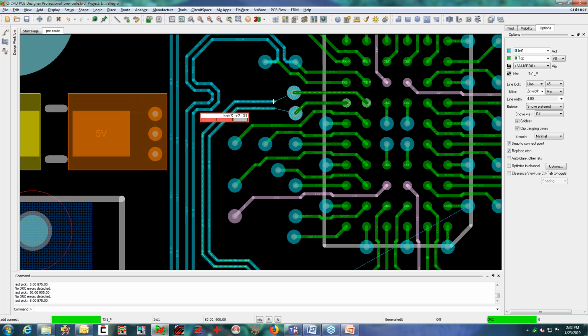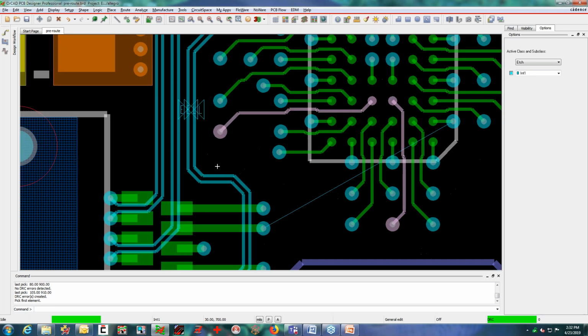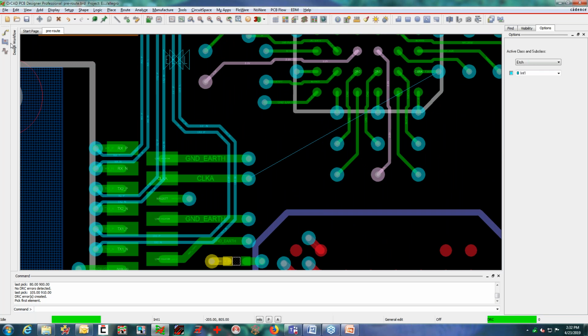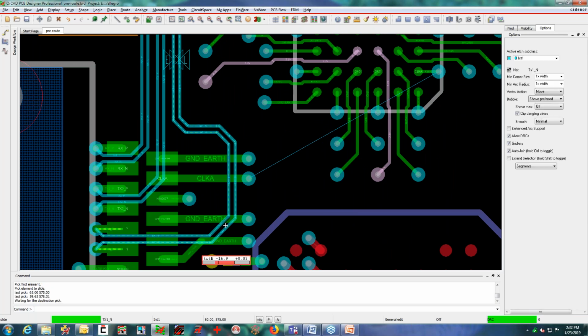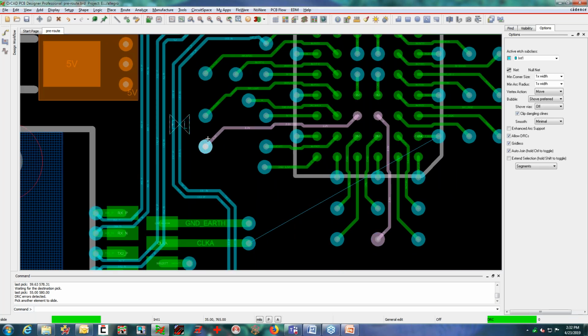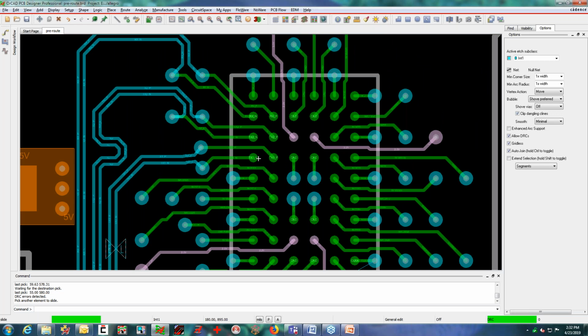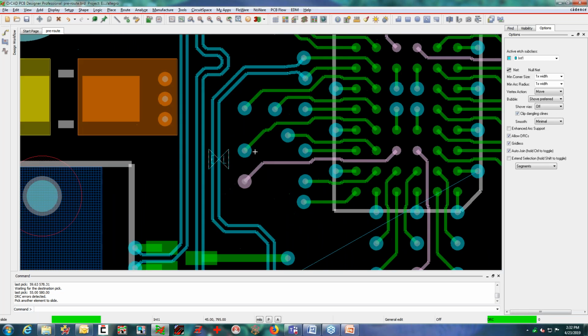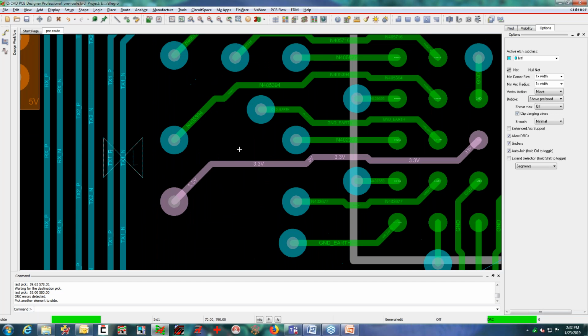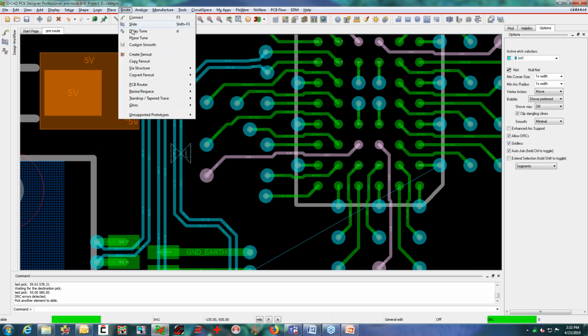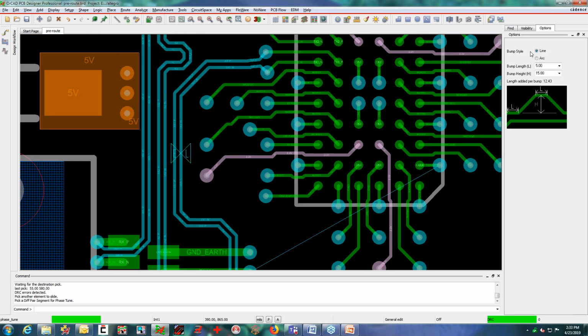And I'm going to back up a step here so I get a better entry. Now this one also has some electrical length issues, so let's go ahead and tune him. Now this one's a little bit more interesting because what's occurred here is this fan out is a little bit longer, so I have a phase problem with this one. So what you can do is use a thing called phase tune here. And over my options, you can add a parameterized bump. So you can dial with these settings, and it'll show you the overall bump size that you're going to get.